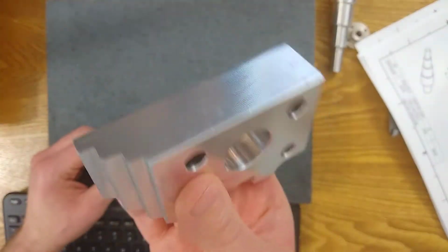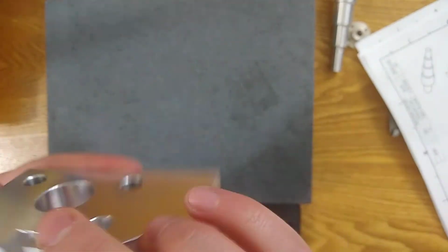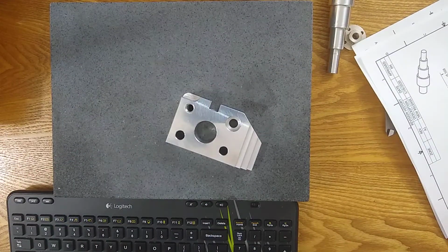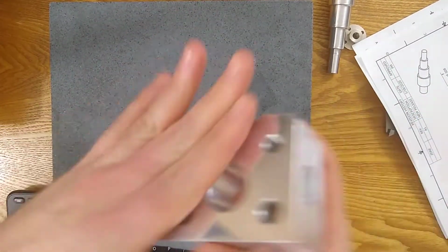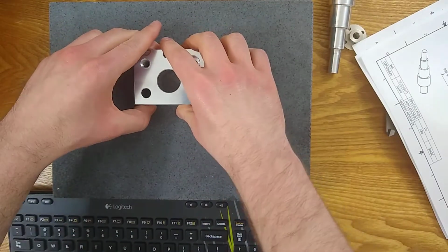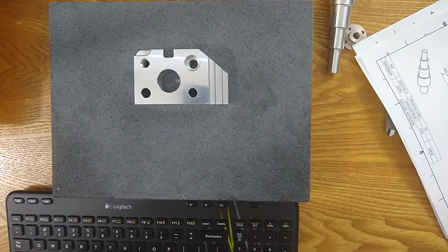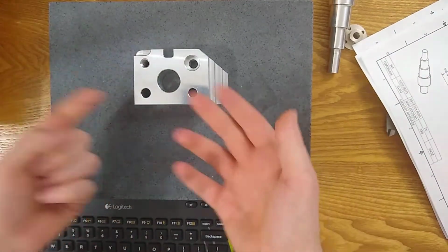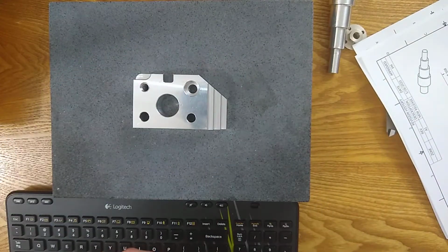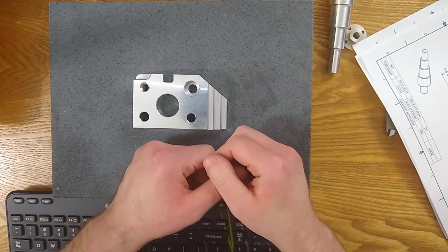When you're doing a milled part and you need to kind of pick datums, what the GD&T standard says is pick the high points. And what that means is you can take a surface plate and take your datum, whatever imperfections are on this surface. When you put it on the surface plate, it sort of gets the high points. The voids are not picked up. The voids are in the part, but the high points are rested on the surface plate.